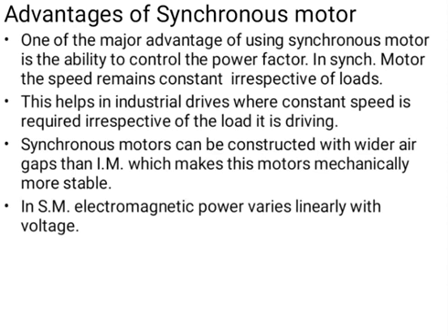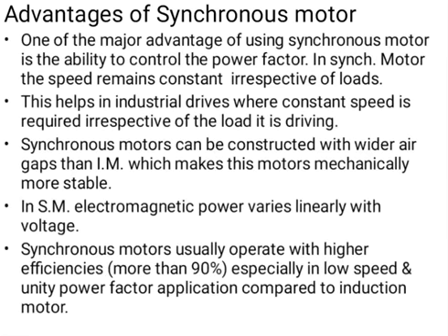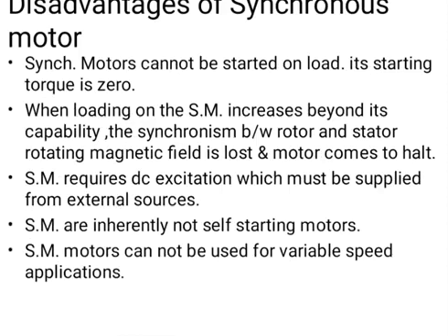Next, the electromagnetic power varies linearly with the voltage. And last, the synchronous motor usually operates with higher efficiency, more than 90 percent, especially in low speed and unity power factor applications compared to the induction motor.